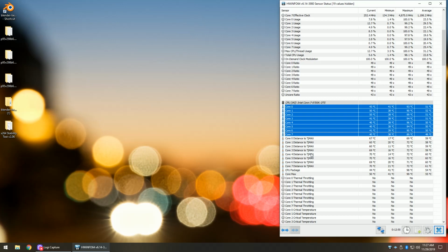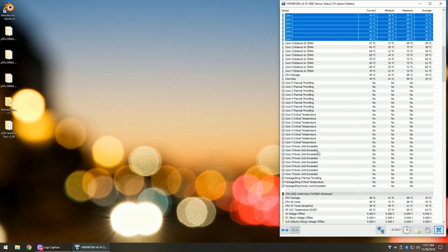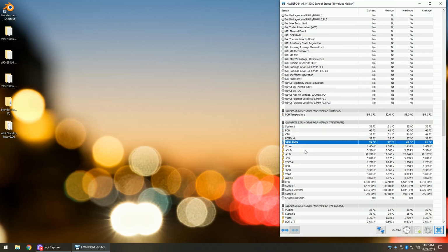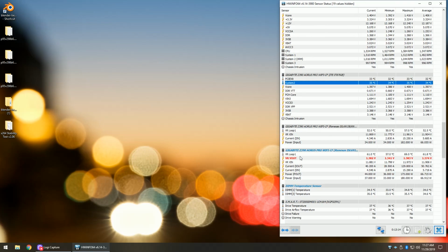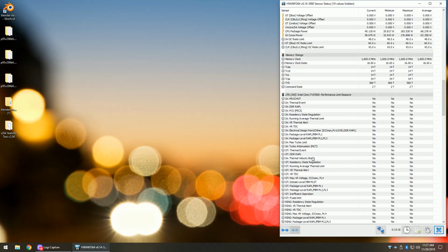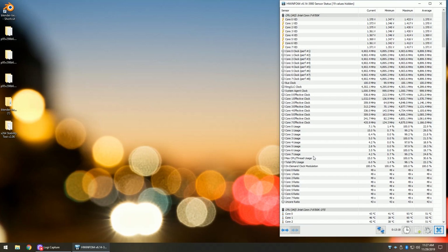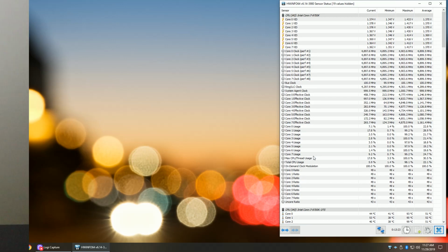My build specifically is using the Dark Rock Pro 4 air cooler, and it's keeping a 9700K under these settings cool. However, there are lots of liquid and air coolers that may not be able to handle certain settings on the processor. Certain processors run hotter than others, might require more or less voltage than others, etc. So that's where the overclocking comes in. You're kind of finding out where your individual sample sits within the silicon lottery.